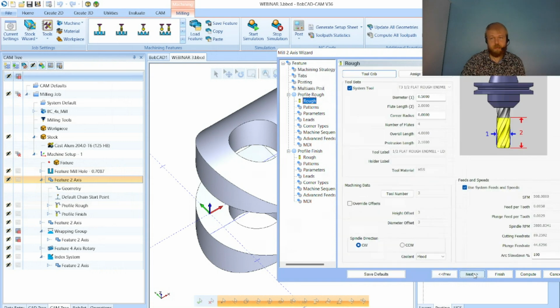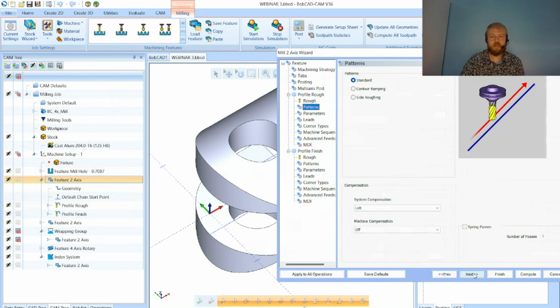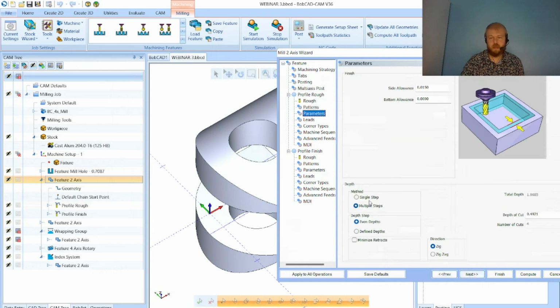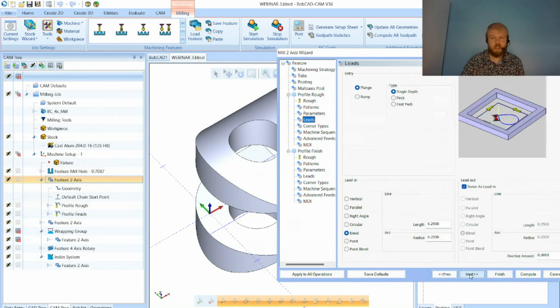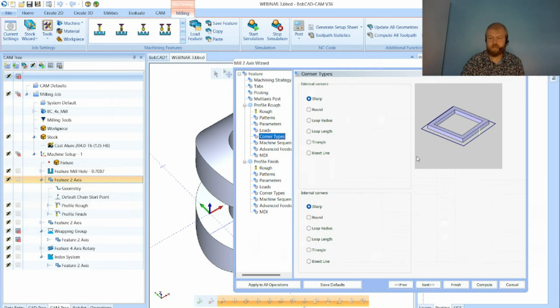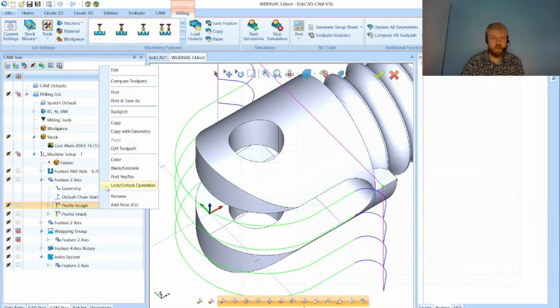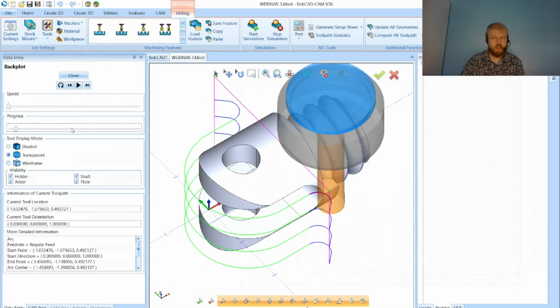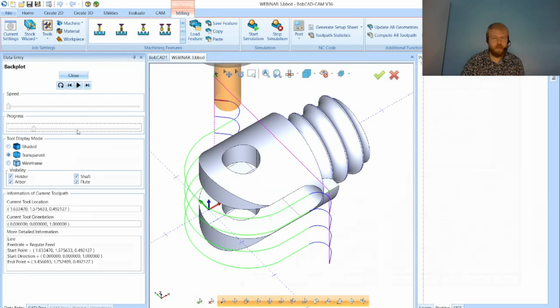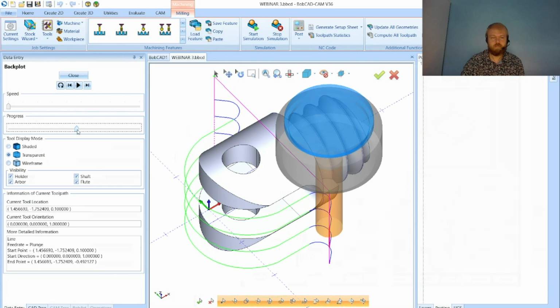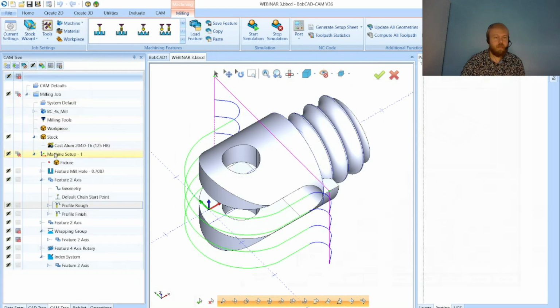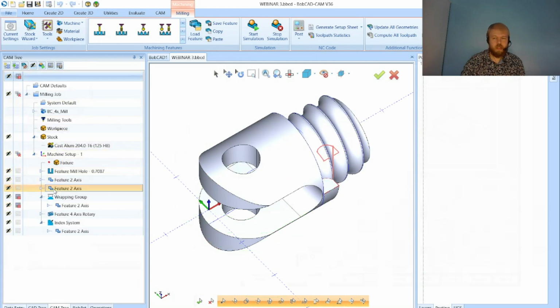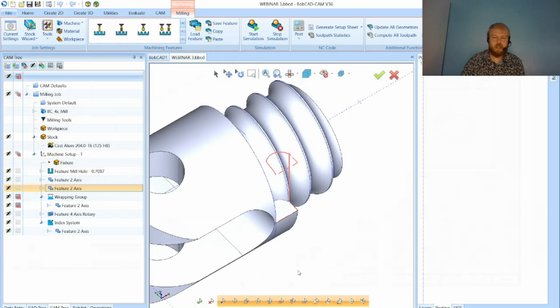I'm going to skip down to setting up my tool, 1/2-inch flat end mill. I did multiple steps down, set a depth of cut for each pass, so it'll be 4 depths. Set a lead in, lead out, those kinds of options here, so that we can go down about 400 thou each time here. Set an arc lead in and lead out at each depth of cut there. Pretty straightforward. Then the next one is pocketing this area here.